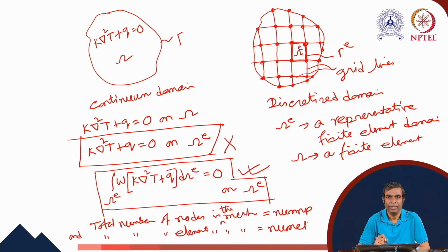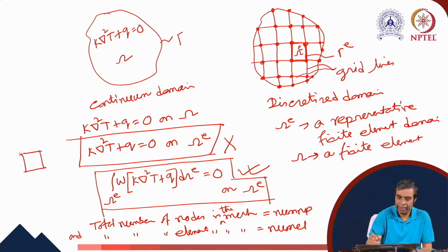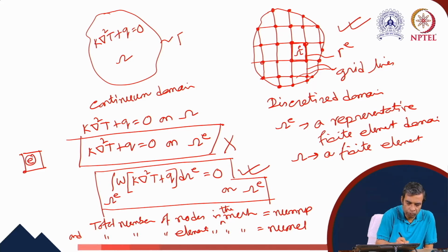These are integer quantities. If we consider a given finite element, for example, the case which we are showing here, the finite elements are of quadrilateral shape. We say these are bilinear quadrilaterals. These have 4 nodes, identified as local nodes 1, 2, 3 and 4.